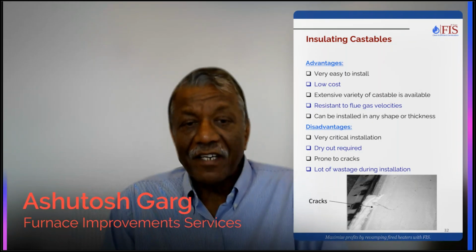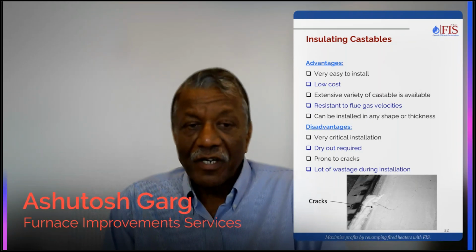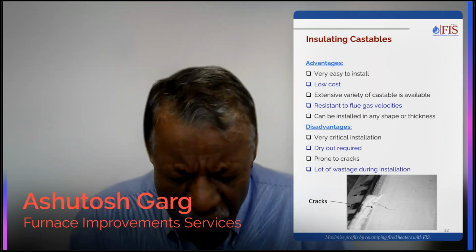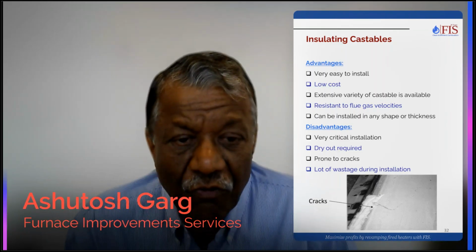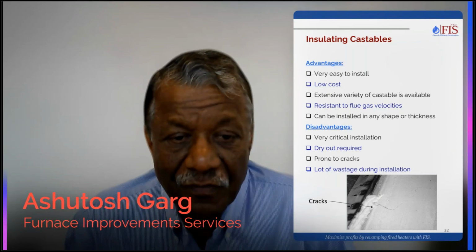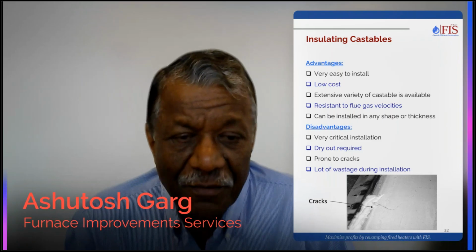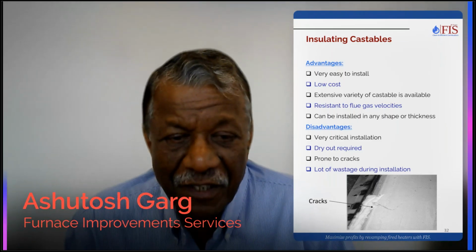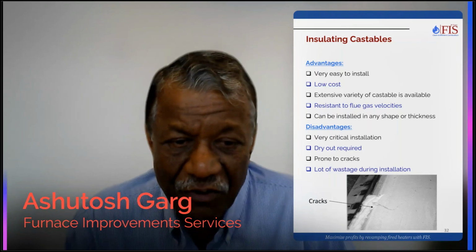One of the critical things is installation. You need to make sure that the water you are using is the right quality and at the right temperature and right amount. Another thing with castables is you need a slow dry out. Typically it takes about 3 days to dry out the castable.